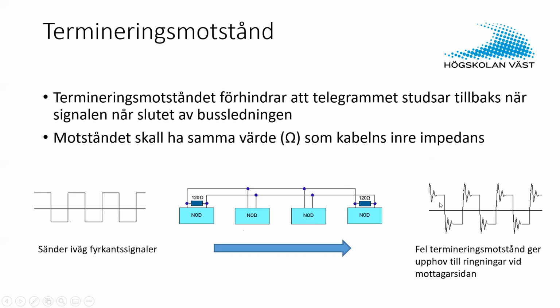This is called ringing, in Swedish ringningar. Without these termination resistors, you will get disturbances, and that could actually make the bus stop working. It's typically only needed at the end.